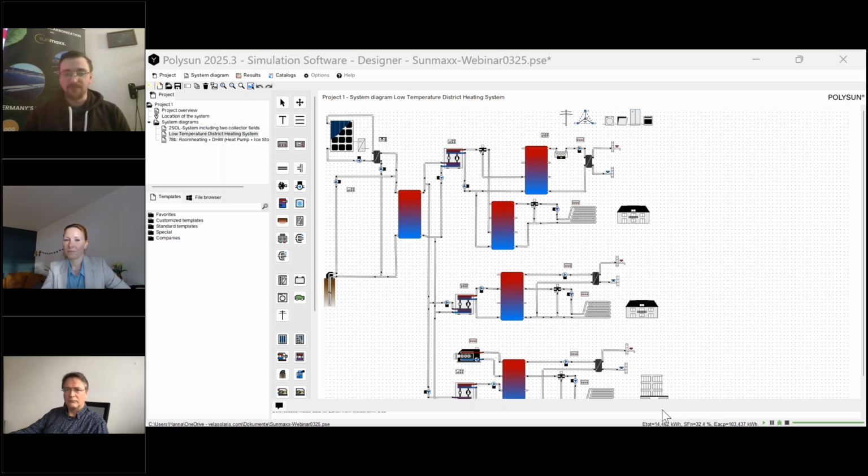So it wouldn't be economical to use the module for the high temperature area. And we have in mind, the higher the temperature of the thermal side, the higher the temperature of the PV side, and with that we would decrease the lifetime of the PV cells. We would decrease the electrical gain. So that's not the way to use the PVT modules.